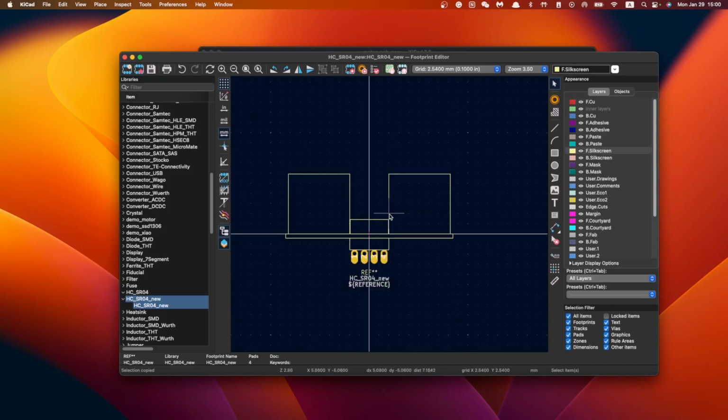And here it is. So what you can do for the next step is definitely not printing it with a PCB machine. In contrast, what you need to do first is to print it on a paper to test whether this footprint fits exactly with your physical device.